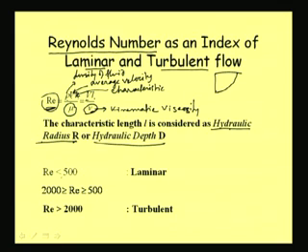Well, this expression we can get for pipe flow. For pipe flow, it is found that if the Reynolds number is less than 2000, then the flow remains laminar. That is what was established in the pipe. A lot of studies were conducted, and you can visualize these things very well in the Reynolds apparatus. In our lab class, we shall try to demonstrate that part also.